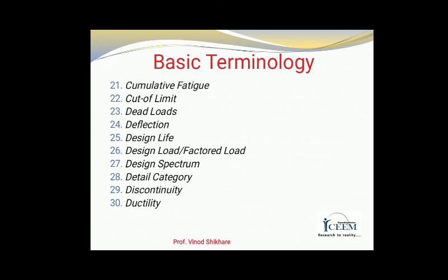Next term is design loads or factored load, a load value obtained by multiplying the characteristic load with a load factor is known as factored load. Then design spectrum, the frequency distribution of the stress ranges from all the nominal loading events during the design life is known as design spectrum or stress spectrum.